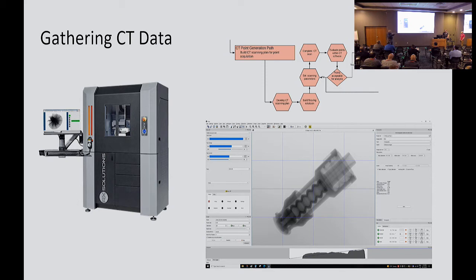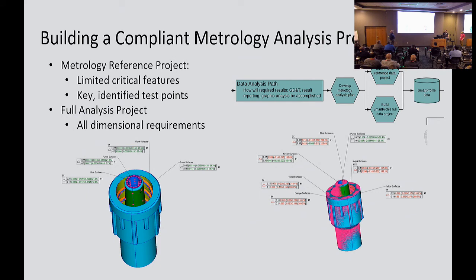So we have to have some way to manage these points and reduce them in an intelligent fashion. And that is in our process, and Adam will talk a little about that. But here's what we would come up with at that first validate the process step. In one hand, I've got this very nice, neat, ordered CMM points, so I really understand that. I feel good about it. I have confidence in those answers. And I've got millions of points, which I've reduced a little bit, to give me the corresponding CT answers.